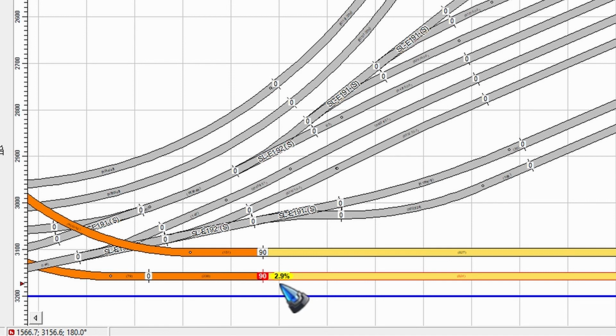That is the rate of climb of this ramp. Right now it is a yellow number. Yes, that is because it is higher than 2.5. Let me rotate the mouse wheel to go a little lower, and then we will see that the ramp below 2.5 is green. That is done because usually in model railways every ramp up to 2.5% is considered to be a safe ramp. Higher than that can be mean trouble to certain engines.